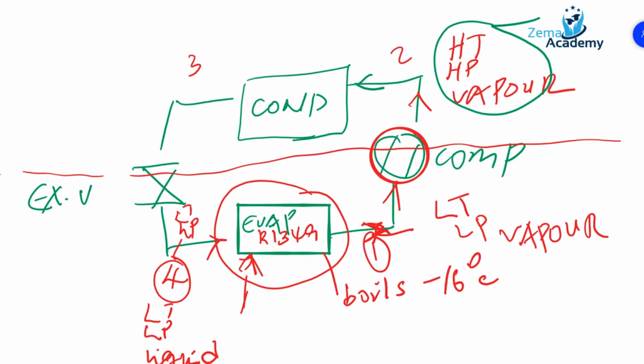By passing it through the condenser, you're sinking that high temperature and high pressure. Here you will have a secondary circuit to remove the heat from the condenser. Again, we will look at whether you're using air or water to remove the heat. That's how a condenser is classified, as either an air-cooled or water-cooled condenser.